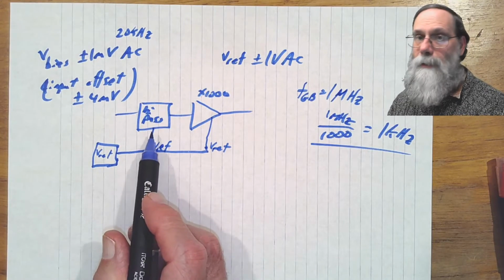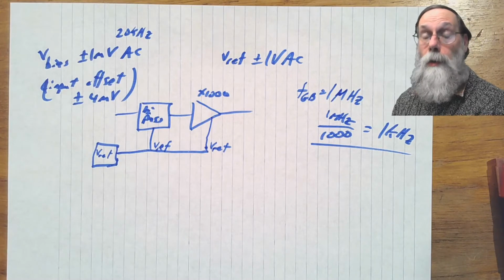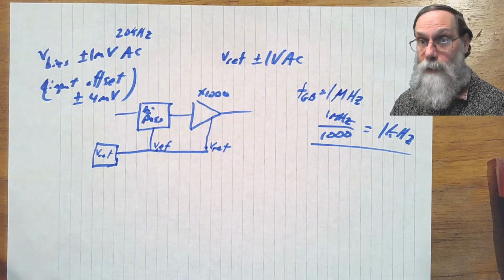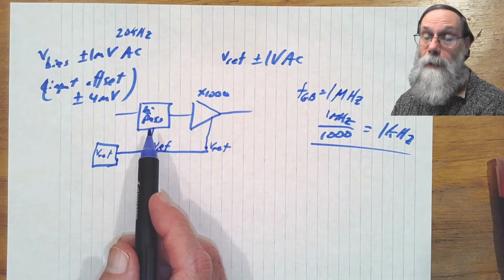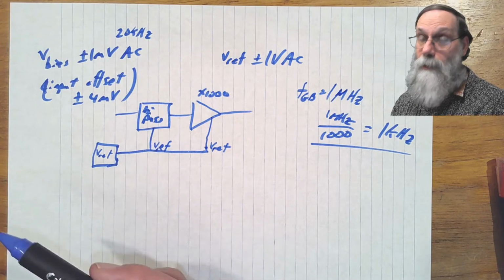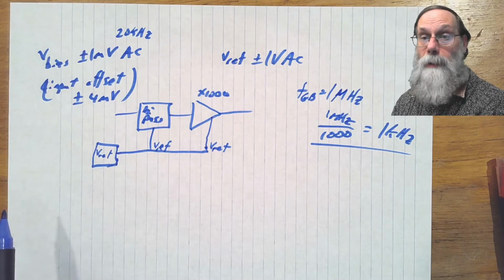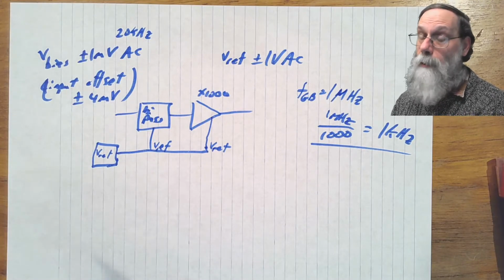We also need to figure out how low a frequency is our signal interesting. Do we care about 1 hertz signals? Do we care about half hertz signals? Tenth of a hertz signals? That makes a difference, because this high pass filter, which is getting rid of the V bias, will also get rid of any really low frequencies. So we have to go back to our original specs and say, what were the ranges of the signal, not just the upper range, what was the lower range of those signals?